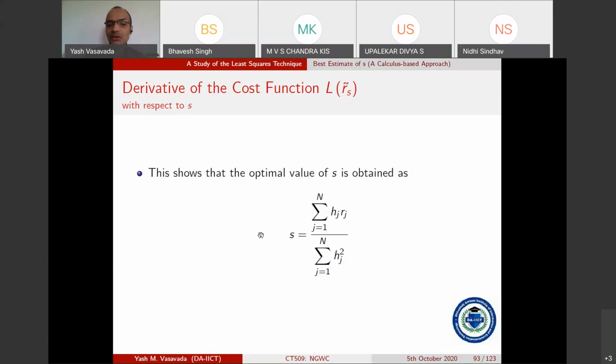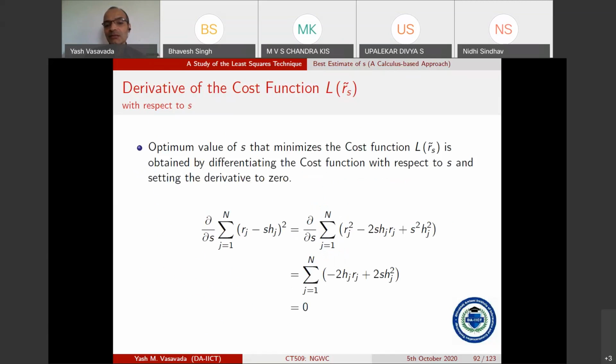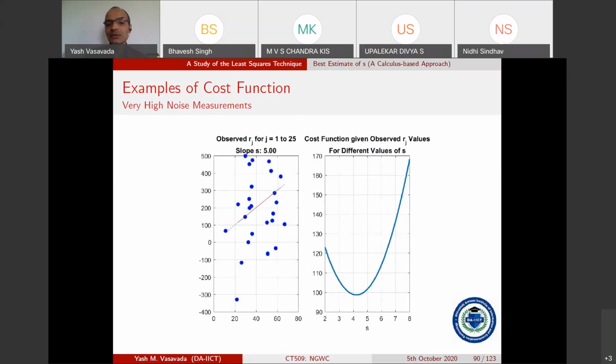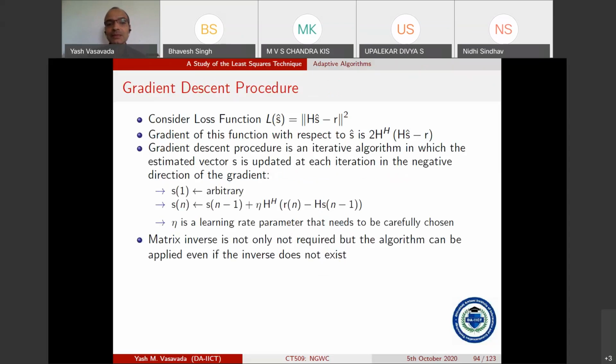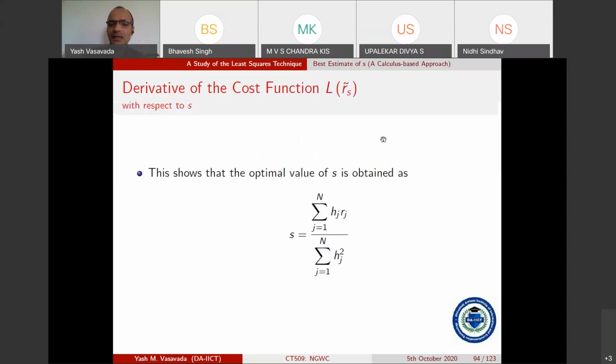So this equation that I obtained through the calculus method and by defining this cost function is identical to the one that I got previously in the linear algebraic manner. So this is another derivation of the decorrelation detection. It allows us to go to the bottom of the cost function in one shot. It just directly gives us the optimal solution. As I was saying, we don't have to necessarily do the entire least squares operation, because for a vector h, this is not computationally intensive.